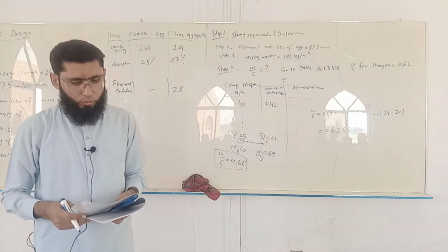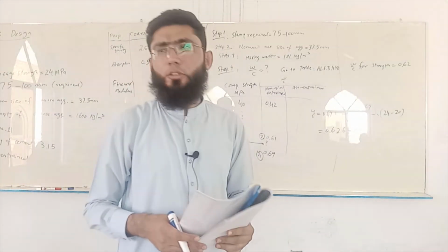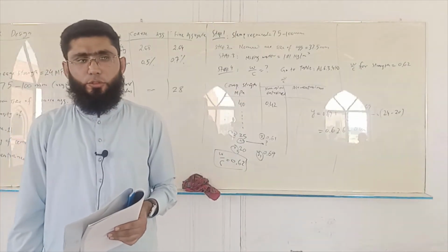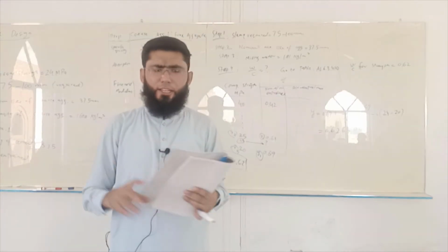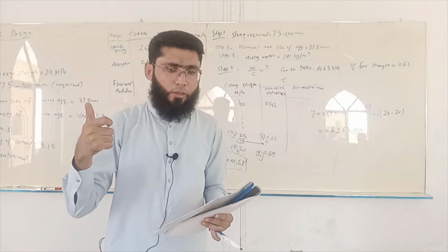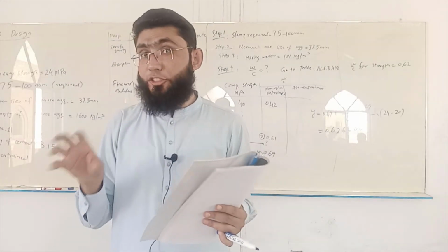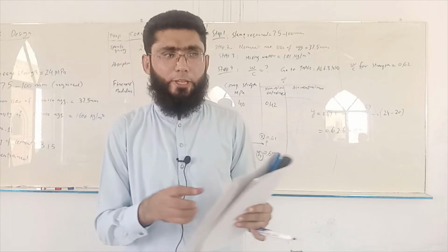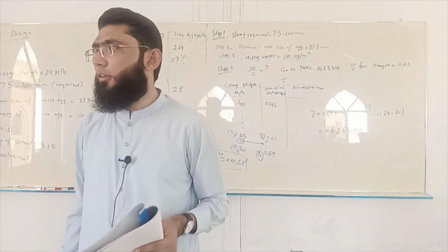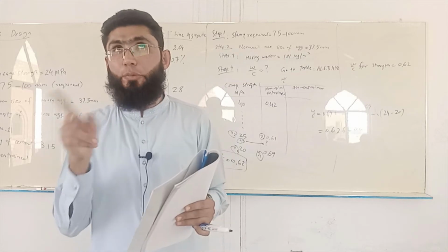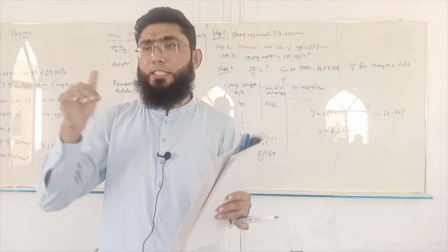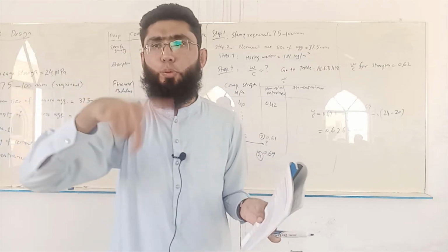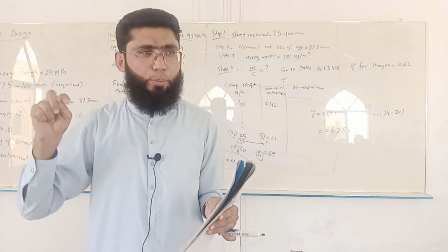Now, concrete doesn't only need to be strong enough; it needs to be durable enough as well. So durability, let me tell you one thumb rule. A stronger concrete, generally speaking, is expected to be more durable concrete. A weaker concrete is expected to be less durable. The reason behind the two things is, one, the higher water cement ratio will give you a lower strength concrete. Why? Because you've got more pores in the cement paste.